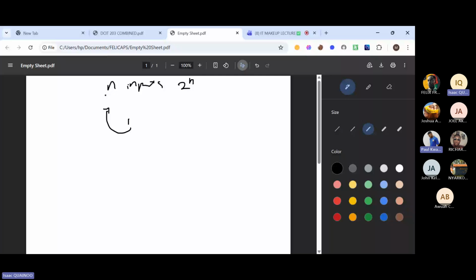So we said that if your selector is displaying 0, 1, then what will be selected is going to be D1. If it has 0, 0, what will be selected is D0. If it has 1, 0, what will be selected is D2.